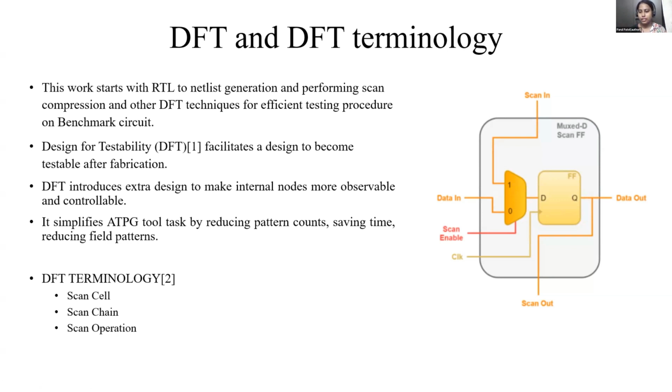We don't have any option to test it internally, like to control its internal nodes. But DFT gives us a feature to add extra circuitry such that we can control its internal nodes. Plus, DFT helps us in saving time, reducing on-field testing. It also reduces the pattern count.